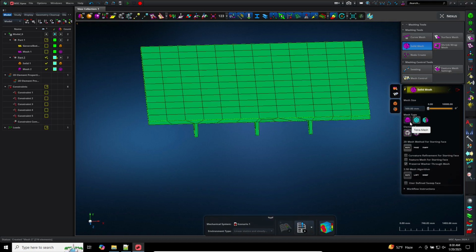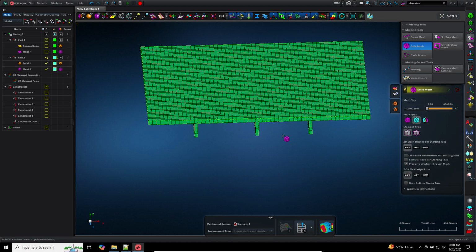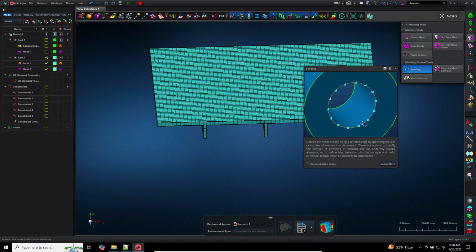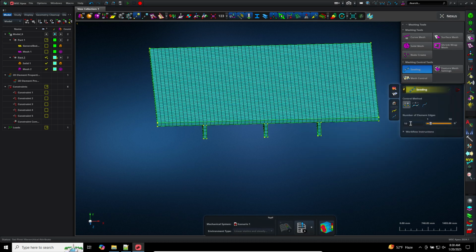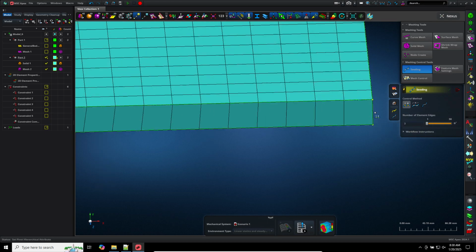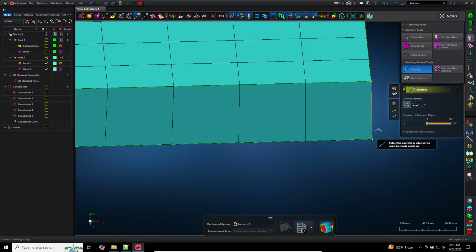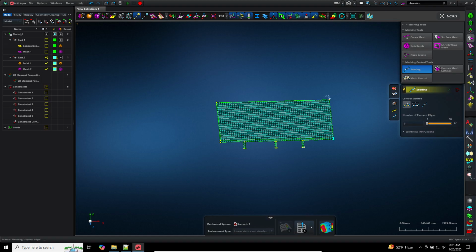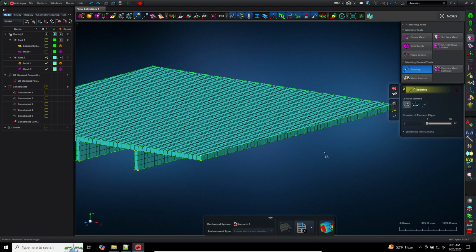What we're going to do is the following. Let's go ahead and turn on the 2.5D mesher. And let's go ahead and decrease the element size to maybe 100. Okay, this is still not okay. One thing you can do is you can use mesh seeds. So let's go ahead and try that. Let's use all these 3 elements through the thickness. So let me click on this edge. So this is something a little better. Let me undo this actually. Let me select the other edge.